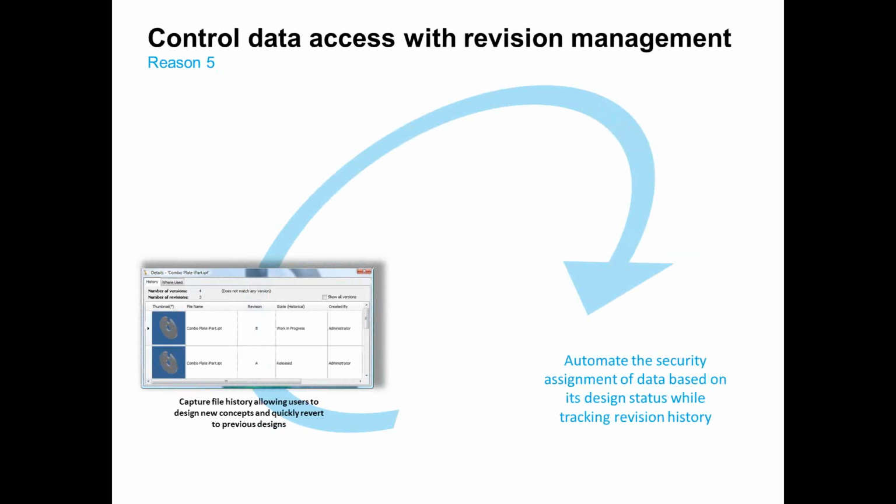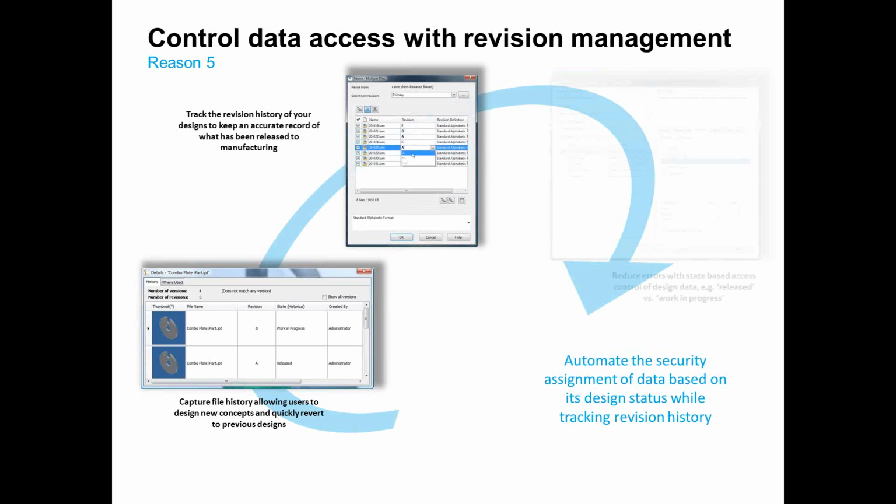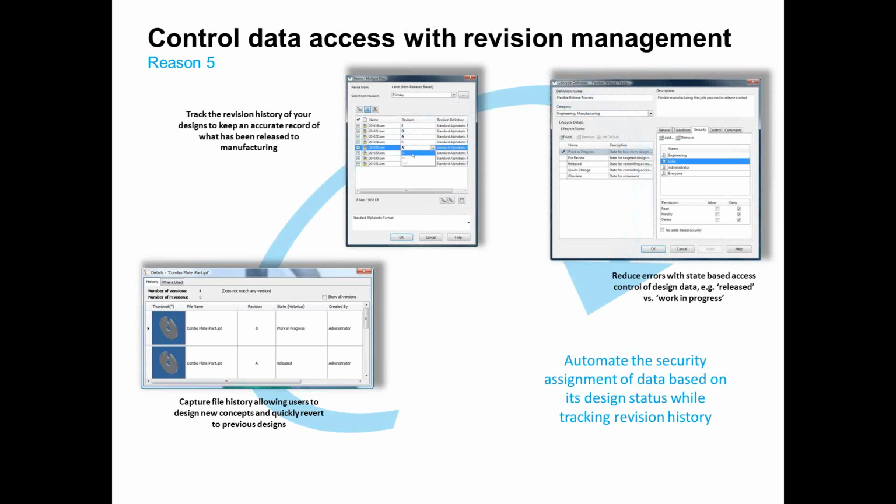Revision and release management is inherent in the higher levels of Vault. Now you can set up your revision management to be a standard numeric or letter-based system, alpha system. Or with Vault, you can also name your revisions based on project milestones, like 30% completion, 90% completion, and then have the ability to go back and access those older revisions and compare. Vault also includes workflow capabilities. So if you have CAD users in your office and then also project managers who need to review and sign off on their work, Vault can allow that to happen through document workflows, which can be set up and used with Vault.